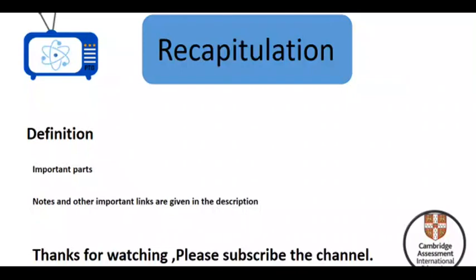Okay, now it is time for the recapitulation. For the recapitulation, the first thing should be the definition. It's very simple. Now you can make the definition by yourself: it is the electrical machine which converts electrical energy into mechanical energy. When we see its parts, it has a pair of bar magnets which produce magnetic field lines. It also contains the coil, the armature, also called the rotor, whose function is to rotate and generate the kinetic energy. It has the commutator, a pair of split rings.